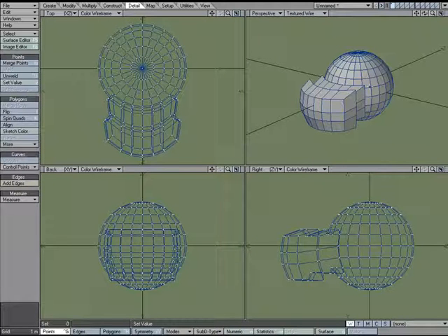So that's just a quick look at set value, found under the detail tab under points, set value, and it's a quick way to set the value for either X, Y, or Z axis for selected points or polygons. What I usually use it for is to make sure that something is on 0x, 0y, or 0z, but you can type in whatever value you want and you'll know that it's exactly where you want it to be using set value.